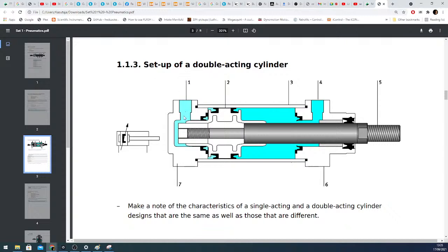We're putting air in from one side and releasing it from the other side, because on the right side we're pushing it out because this volume here gets smaller, and we're letting the air in from the other side, and it flows into the cylinder. When the cylinder moves, this volume here gets larger, so we need to fill it.